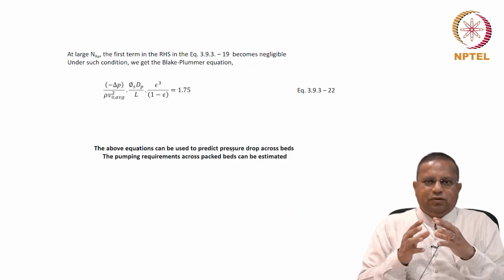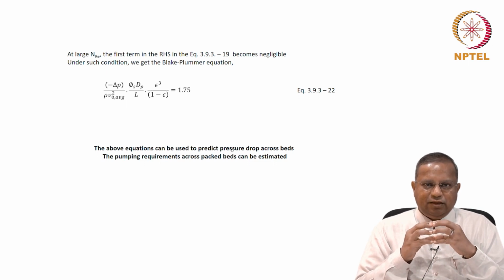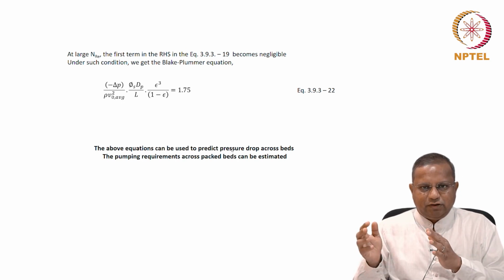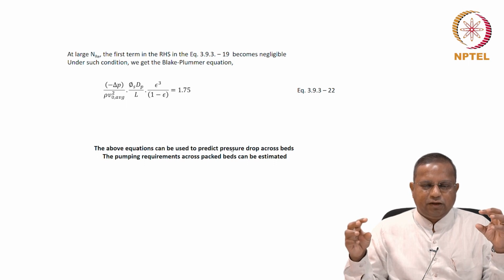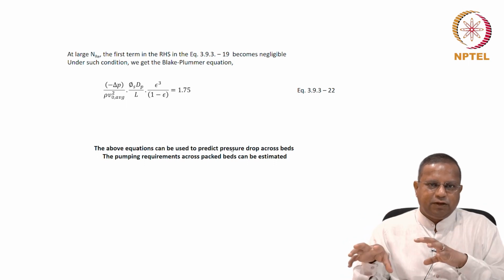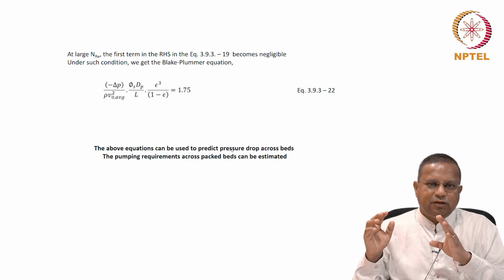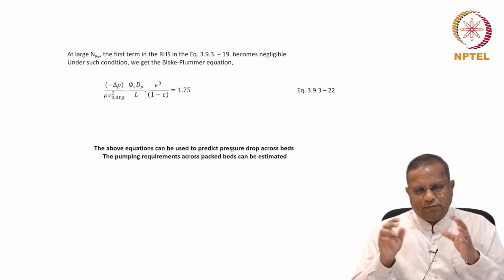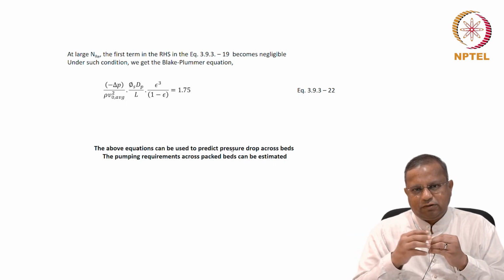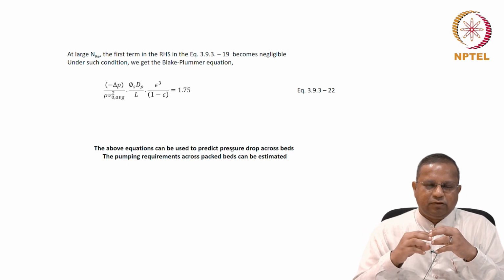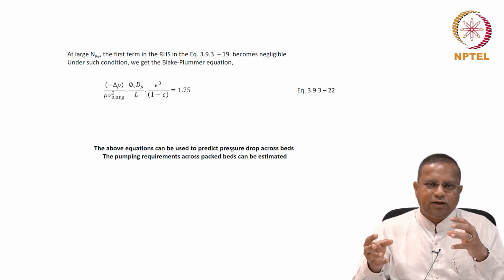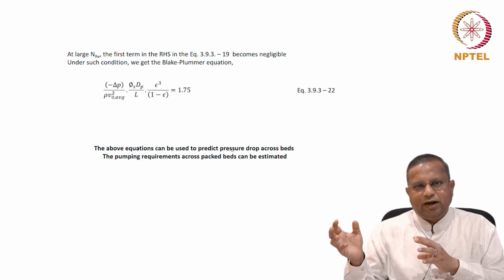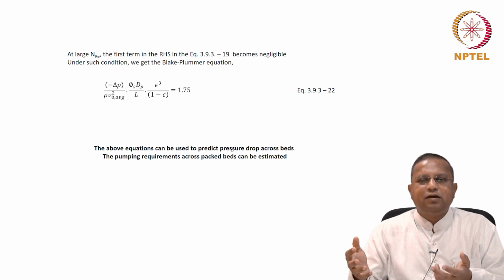And so we have seen the application of the friction factor approach to various different situations: to a piping network consisting of straight pipes and pipe fittings, to a contraction, a stenosis in a biological situation, for relative motion between a solid and a liquid, and now packed beds. Packed beds are very widely used.